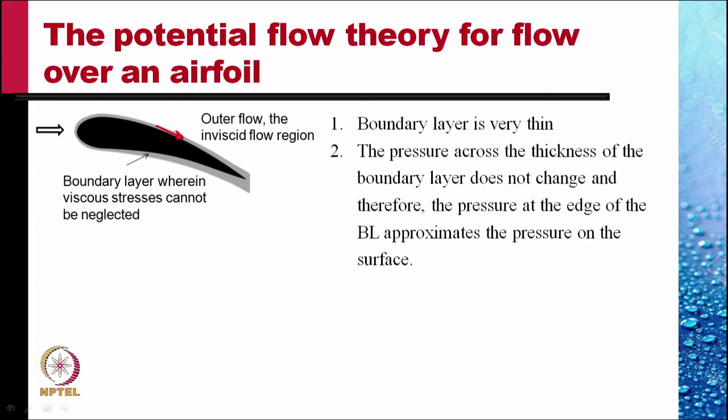But the boundary layer is very thin, and if it is thin, to the first order approximation, we can neglect this at all, so that we can treat the outer flow as first approximation to extend right up to the surface of the aerofoil, provided the boundary layer is thin, that is, the flow does not separate. That is, for low angles of attack on a rounded nosed aerofoil.